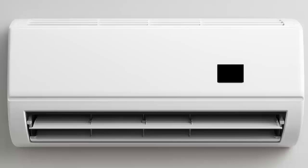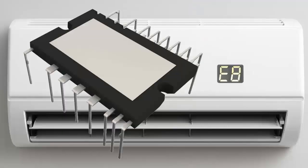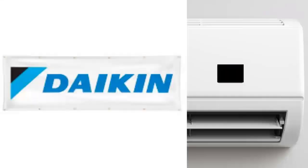A. In several brands, error E8 indicates that the compressor is receiving more current than it should or has overheated. This may be due to internal compressor failures, issues with the electronic control board or the IPM, intelligent power module, which powers the inverter compressor, or in some cases, insufficient heat exchange in the outdoor unit.